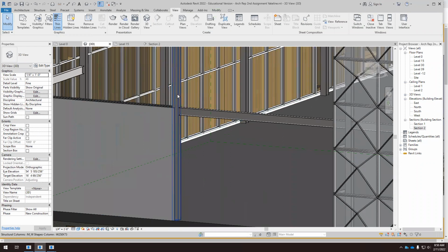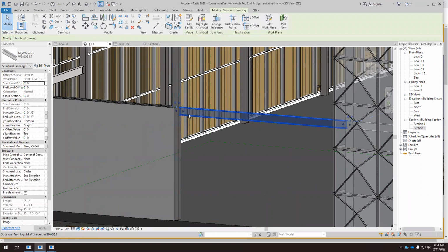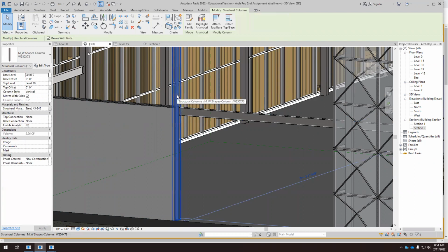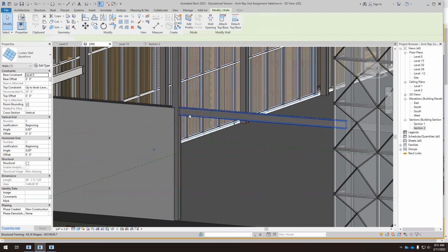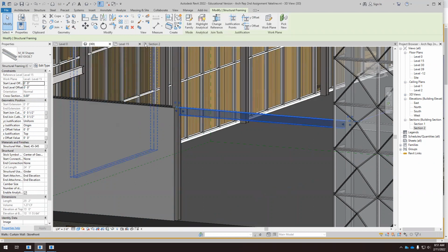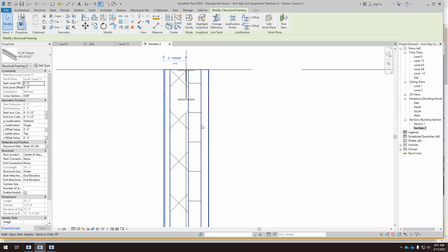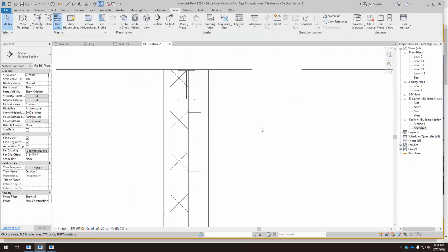Okay, so we have the steel column, and then we have the steel beam. So we have to deal with the steel column in the plan, and we have to deal with the steel beam in the section. So what's the right position for this element? Remember that this is the concrete masonry unit. Then we have the thermal insulation, air cavity, aluminum, and here we have the air cavity with the metal furring, and here we have the gypsum board.